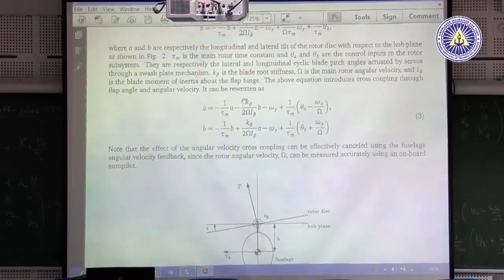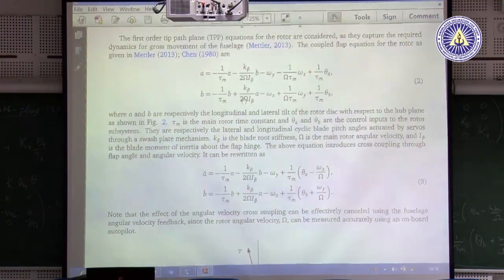So this omega x and omega y, you see, A is primarily affecting omega y, but there is omega x also coming in, and you have B. These are the two cross coupling terms in these equations, and that is why when you have a motion in one direction, it automatically excites the other.